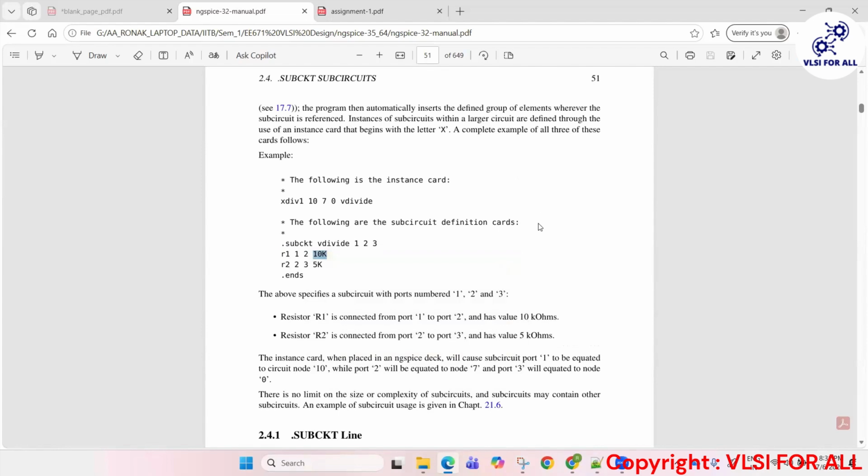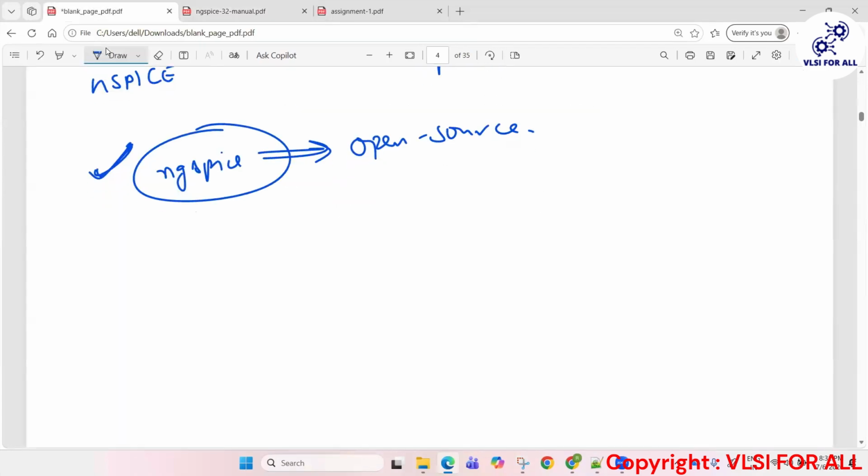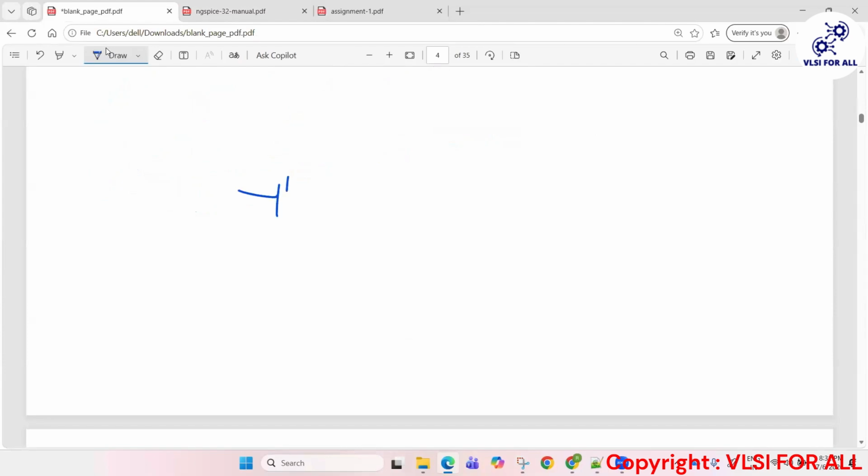Depending on the nodes of the circuit, let's say I take this MOSFET, with ground, and there is one capacitance with ground, something like that. What you will do is give names to each port. This is one, this is two, this is three, this is four, and this point is also one because it is connected with the same wire.